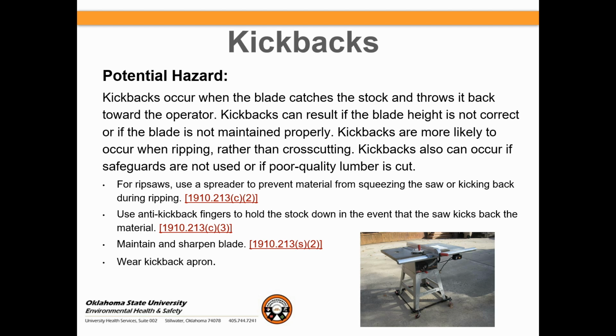Kickbacks are more likely to occur when ripping rather than cross-cutting. The other thing too is kickbacks can occur if safeguards are not used or poor quality lumber is cut. This is what you use rip saws for.